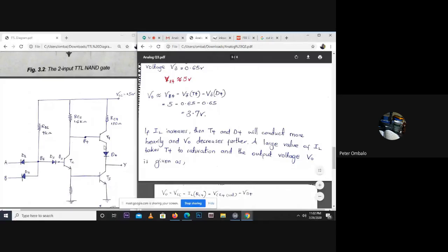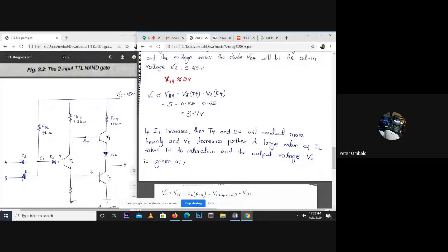So just to recap, we are at our case 2. Transistor T4 is in conduction. Transistor T3 is in cutoff. So now VB4 was given as approximately 5 volts. To get the voltage at the load, it will be approximately the voltage at B4 minus the voltage that is going to be dropped here.